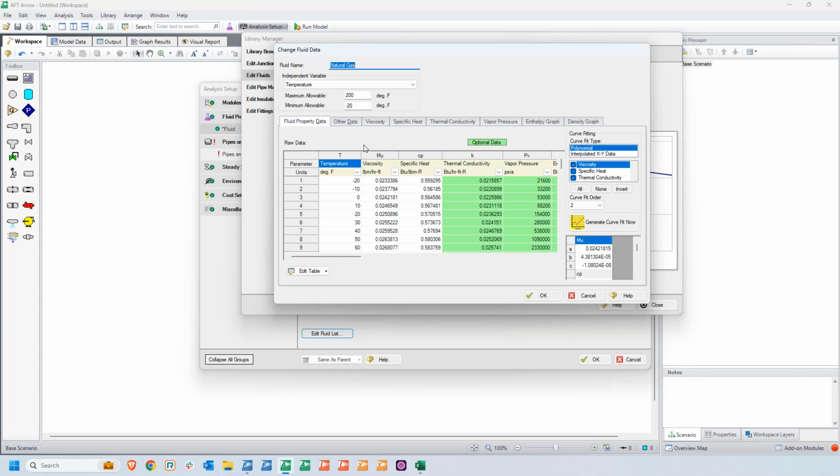It's always okay to use approximations, but what's important is to remember the assumptions that you're making when you're using these approximations. If you are using any approximations that may deviate from what the real system is doing, it's important to know ahead of time how that may impact your calculations, what kind of safety factors you may need in order to properly account for that, and use your best engineering judgment to make sure your model is as accurate as it can be with the data you have available.